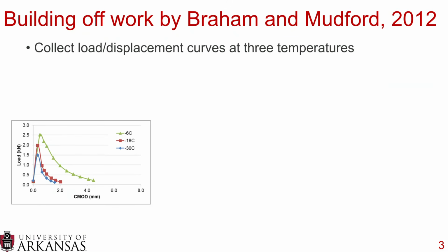So the work that they did was built off work that I did with Caleb Mudford, who was a fantastic undergraduate student way back at the beginning of my career in 2012. And what we did is we took some of the data I'd collected during my PhD thesis at the University of Illinois under Dr. Bill Butler. And what I had done there is I collected a whole bunch of DCT data, dish-shaped compact tension test data, at 3 different temperatures across various mixtures. And what we did is we collected the load displacement curves and then we calculated the fracture energy while I was at Illinois.